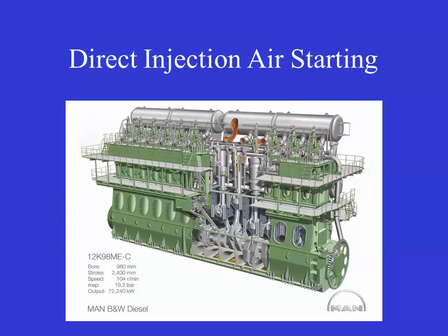The size of the bottles is very dependent on the size of the engine. And what's going on is you're injecting air into the cylinder at the proper time to turn it in the proper direction. Instead of burning fuel to have that force pushed onto the piston, you are injecting air directly into the cylinder.